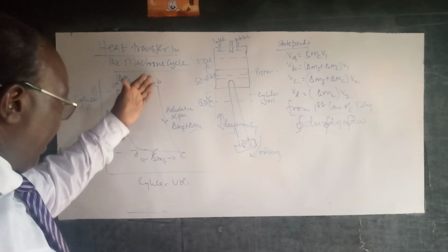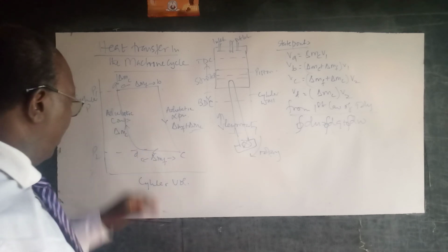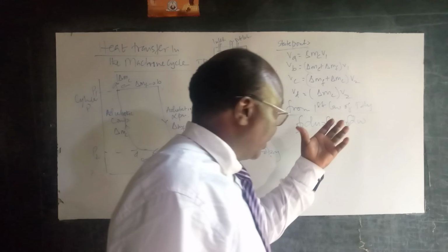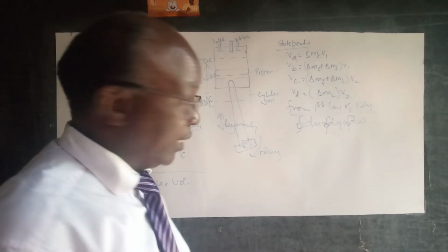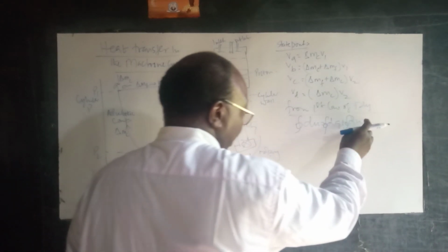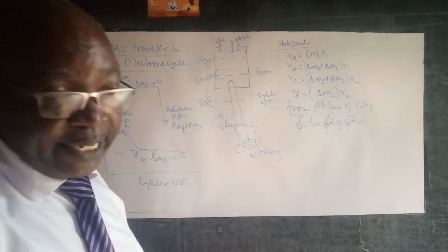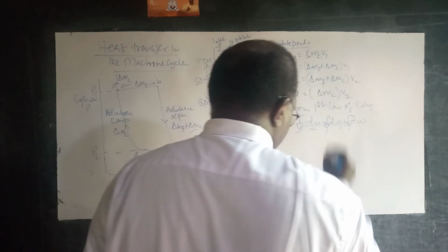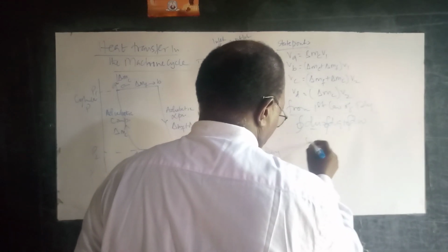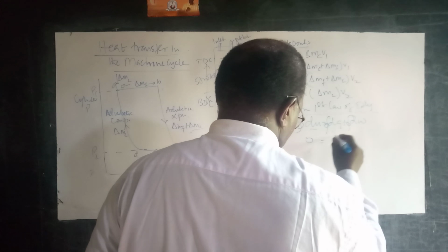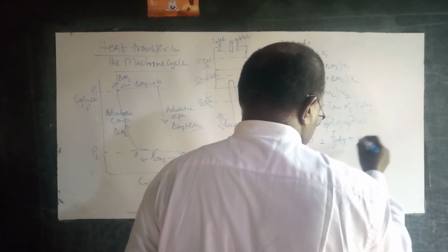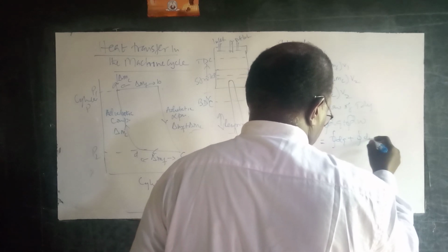That's for process A to B, B to C, C to D, D to A. I encourage you to look at our discussions on the Carnot cycle, where we've discussed extensively these cyclic integrals and the line integrals. Each cyclic integral here has four line integrals. And we know that du is a state function, so a cyclic integral is basically 0. So we are left with cyclic integral dq plus cyclic integral dw.